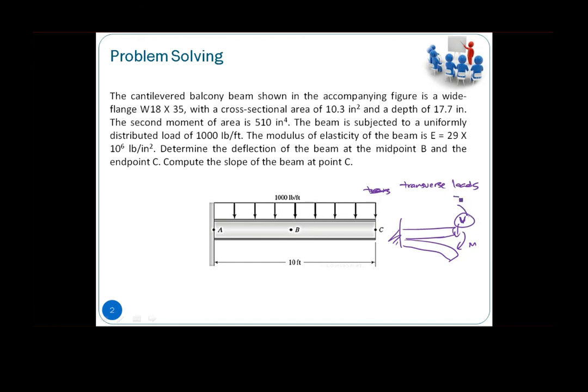So these will actually generate a shear stress, as well as the moment that generates your maximum normal stress. Right, so that actually combines. So when you are doing your mechanics of materials, for a beam subjected to a transverse load, you have to look into shear as well as the normal stress, or shear from the shear force itself, right?